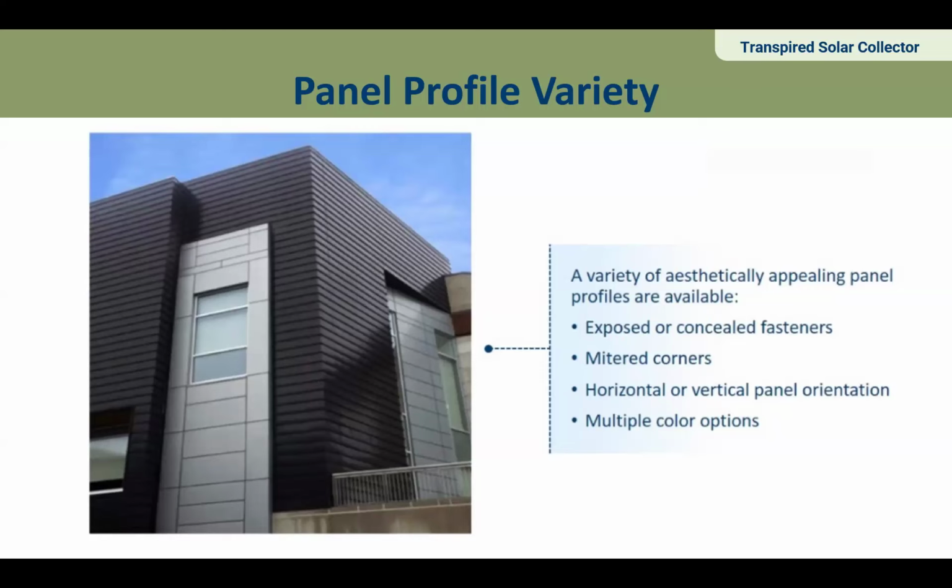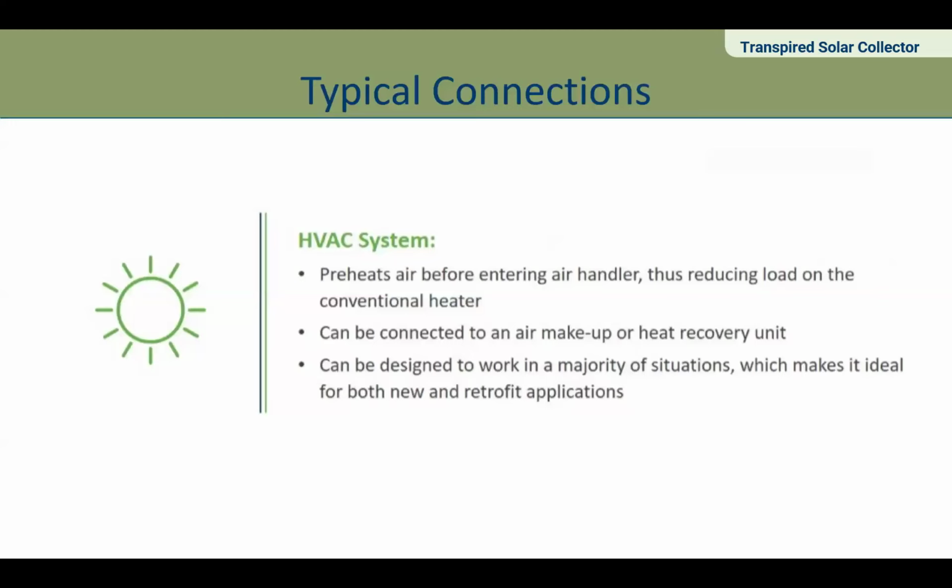But with this, just because of the framing and everything, sometimes we're asked, how do we handle all the architectural details with trims and corner conditions and so on and so forth? And all of the same options available in a conventional single skin wall design are available in this system as well. Requires a little extra framing at the corners and stuff like that, but everything is achievable with this system that you would otherwise get in a single skin application.